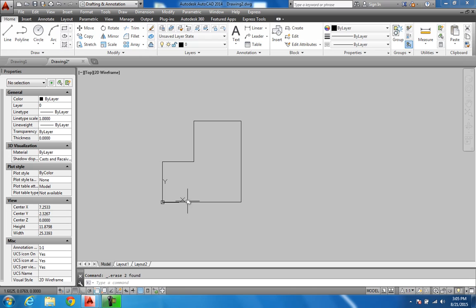And there's a few more little extra quick techniques that's involved, and we'll show it to you as we progress. Don't want to put too much on you at first. But that's the absolute line method. You just have to know how to utilize that Cartesian coordinate system. And for me, working on a project, I like to keep everything positive, or going off of a center point to your dimensions. It seems like it works a whole lot easier.